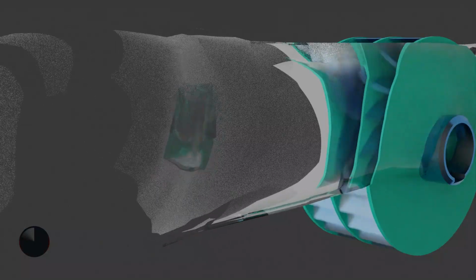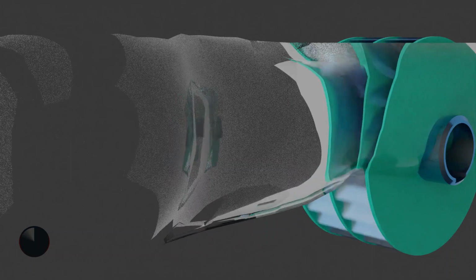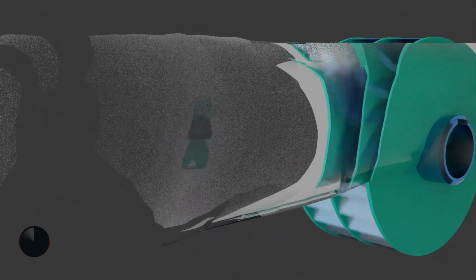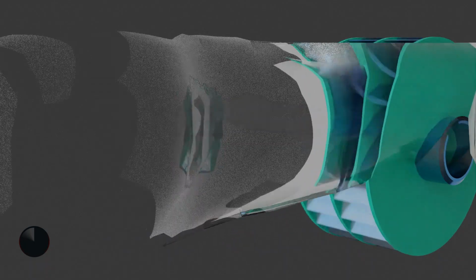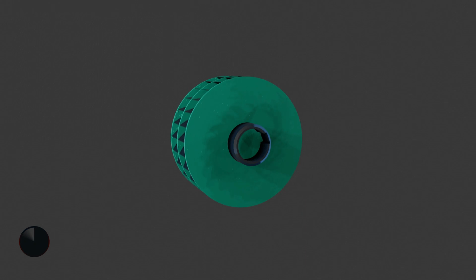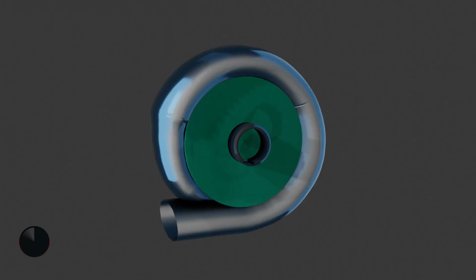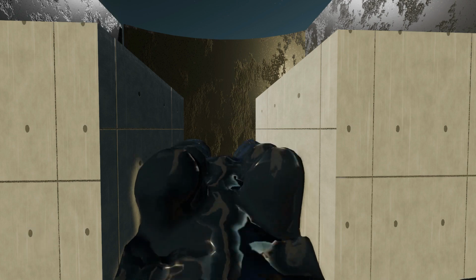The cross-flow turbine allows water to flow through the blades twice. On the first pass, water flows from the outside of the blades to the inside, while on the second pass, water goes from the inside back out. A guide vane at the entrance to the turbine directs the flow into a limited portion of the runner. The cross-flow turbine was developed to accommodate larger water flows and lower heads than the Pelton can handle.